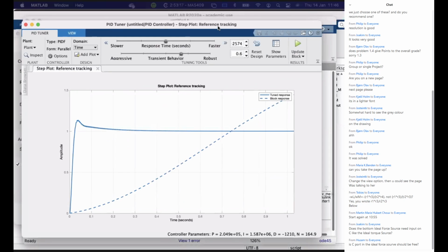Yes, so now I have it. It's easy to forget one small reference and then the whole simulation is not running. But then here I can, for example, choose my frequency, the phase margin, so 60 looks good. And then it will auto-tune, in less than 100 milliseconds it will reach maybe the settling time. So that's good. I can update the block.